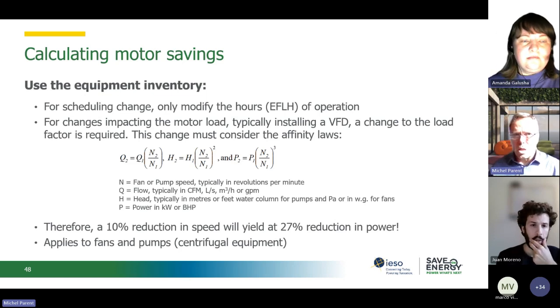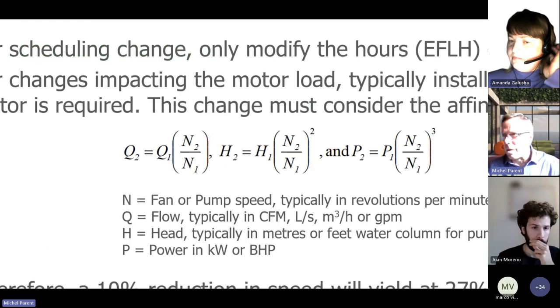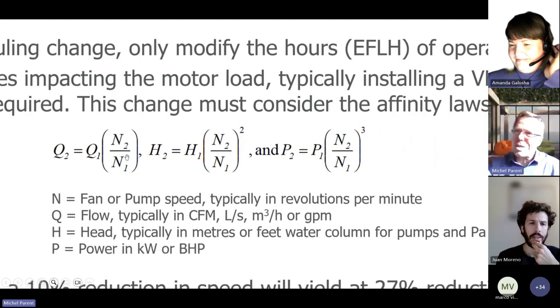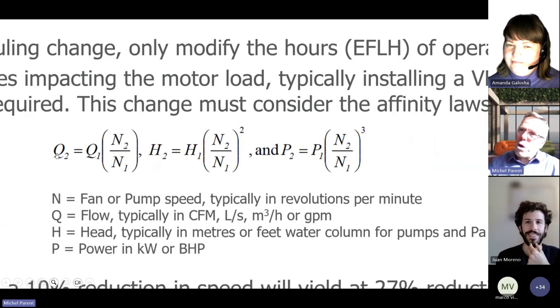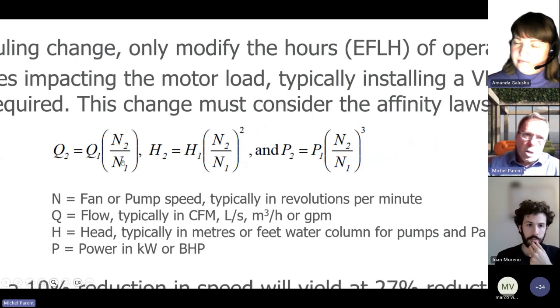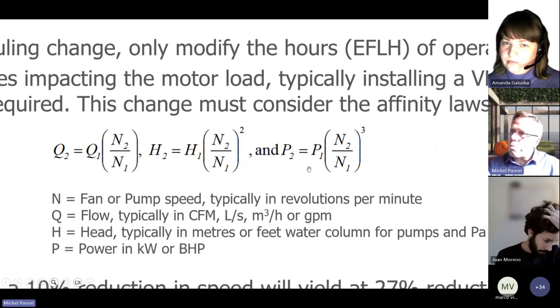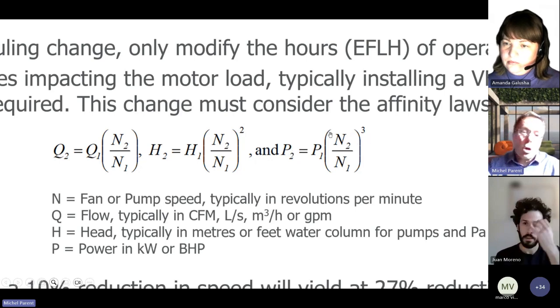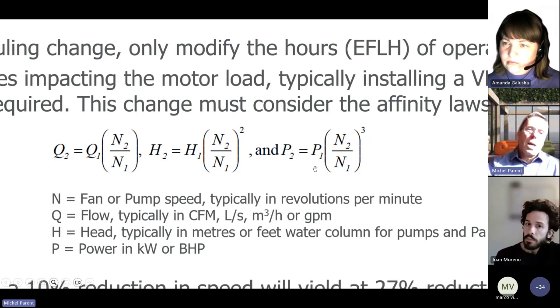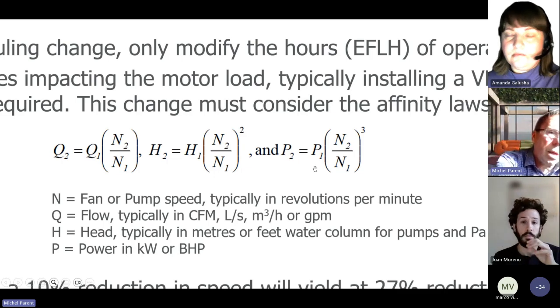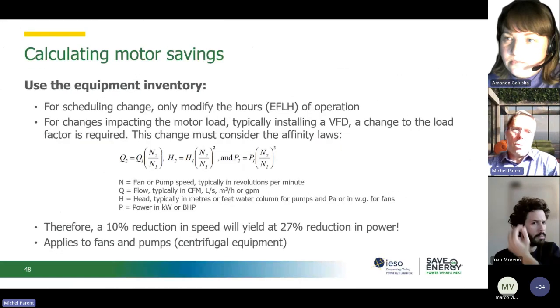the VFD speed. So your savings calculation can be based on, and I'm going to zoom on this here, the kind of scary affinity laws. I say scary, I should not say that. Your flow will vary to the same proportion as the speed. Forget the head here, we don't care about that one. But your power will vary to the cube of your speed change. So those are the equations you need to apply when you go to a VFD.